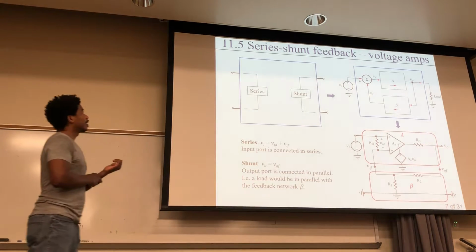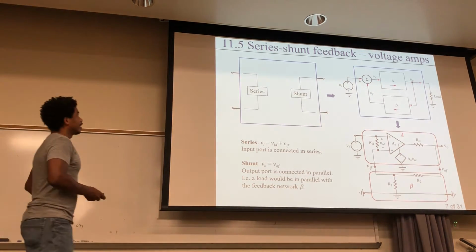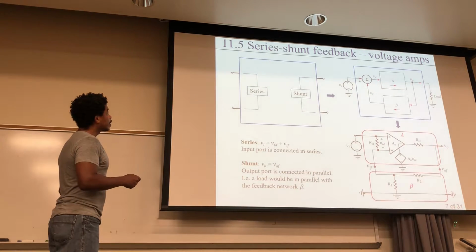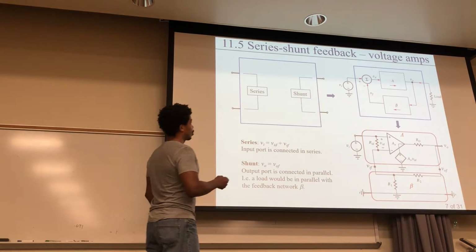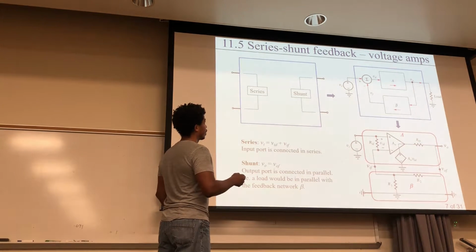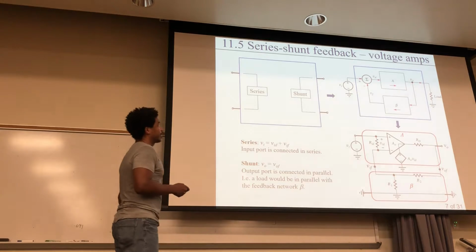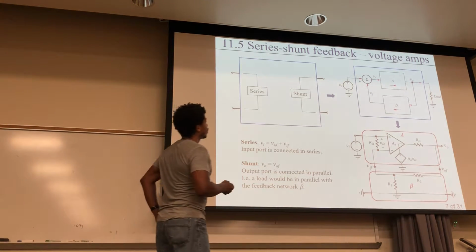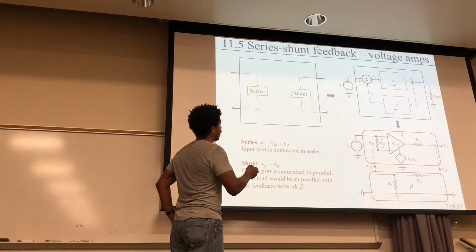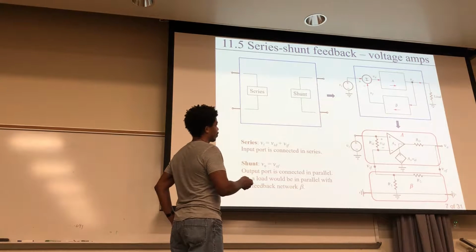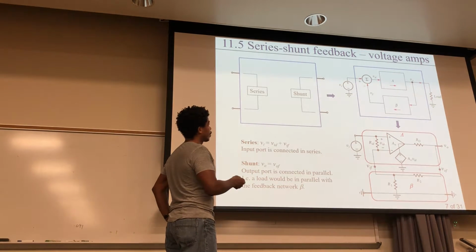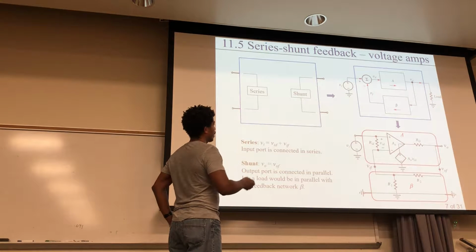Okay, so one more way to look at it. You can have this 2-port type of abstraction, and also look at it in terms of your feedback loop, because it is a feedback loop. It's an op amp in this case. You have this VD coming in. This VD right here is like your VID going into your op amp. These things summing together is like this coming in right here, summing to that. So this is negative feedback. That's why you have the negative sign there.